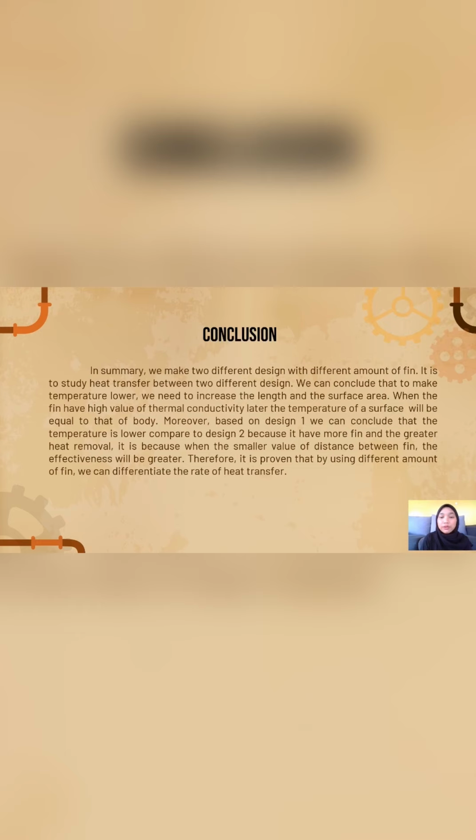it has more fins and greater heat removal. It is because when the distance between fins is smaller, the effectiveness will be greater. Therefore, it is proven that by using different amounts of fin, we can differentiate the rate of heat transfer.